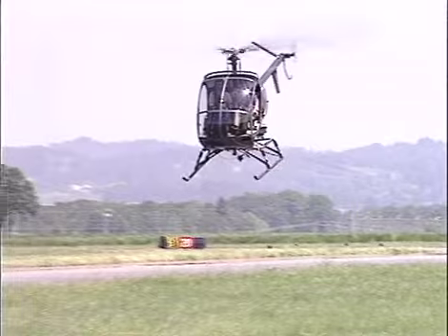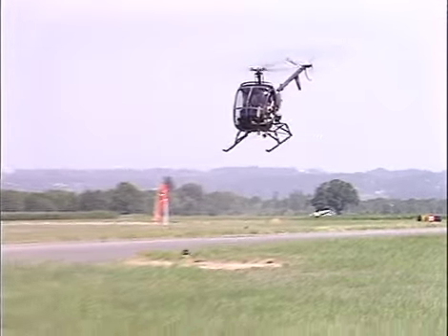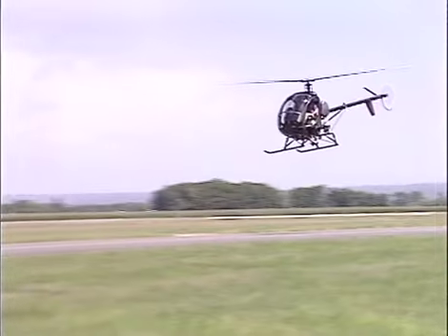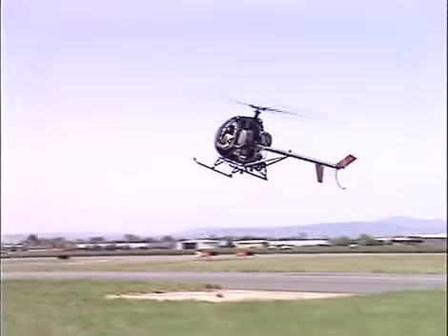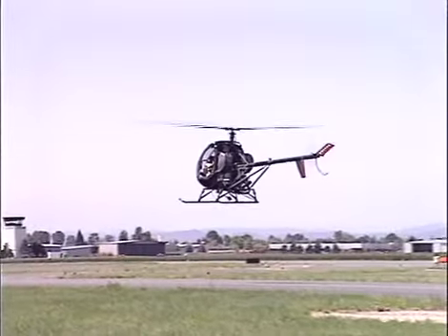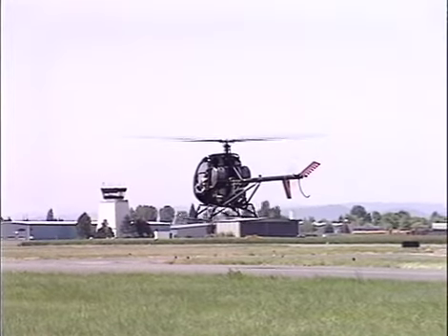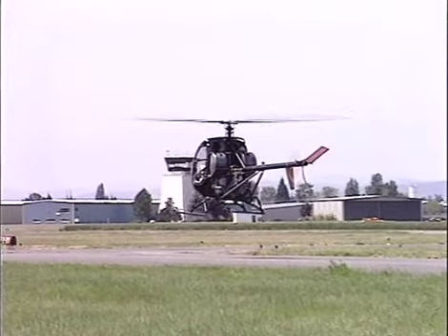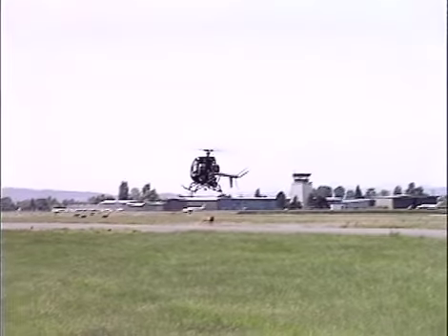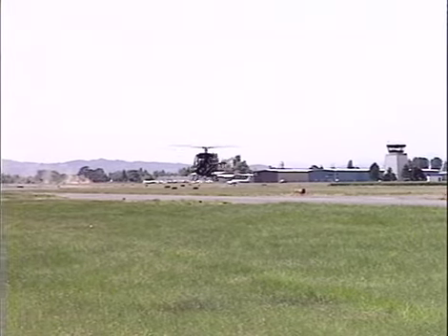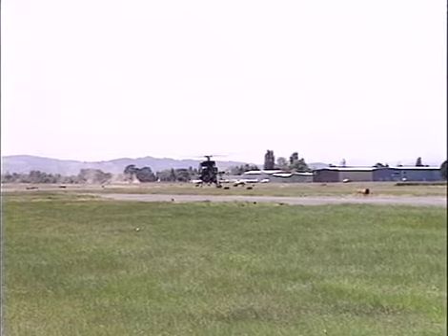Two, you may find yourself in a situation where you'll literally need to put on the brakes. You might be air taxiing across the airport when all of a sudden another aircraft cuts in front of you. Knowing how to stop quickly and smoothly could make the difference between a close one and a pileup. Three, the quick stop is very similar to the flare portion of an autorotation. If you're knowledgeable and practiced in quick stops, the chances are better that you'll perform a safe autorotation when it counts.